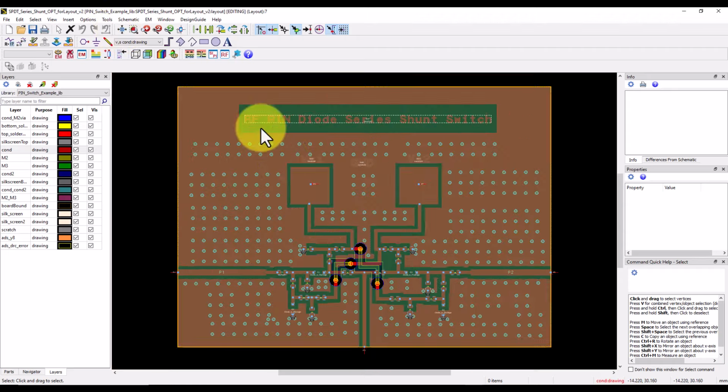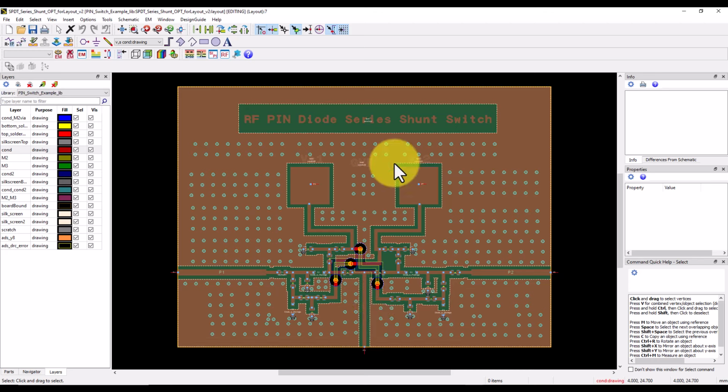Again, this will have performance Y. The performance X could be worse than performance Y. This layout might be much better performing because you are controlling the length of these transmission interconnects, which essentially would cause a certain amount of parasitics in your actual response at higher frequency.